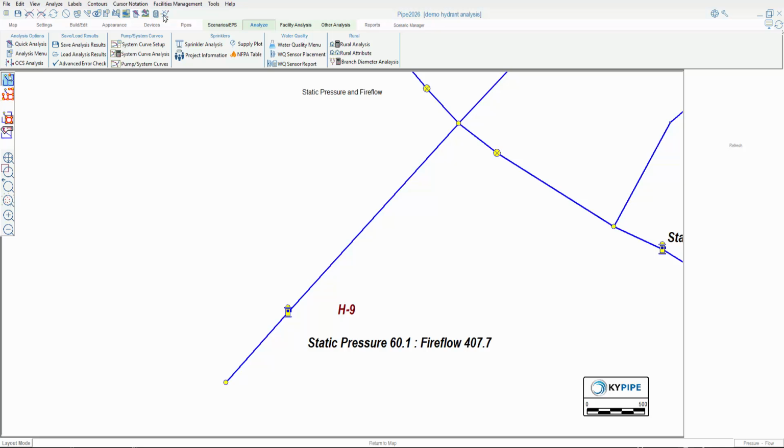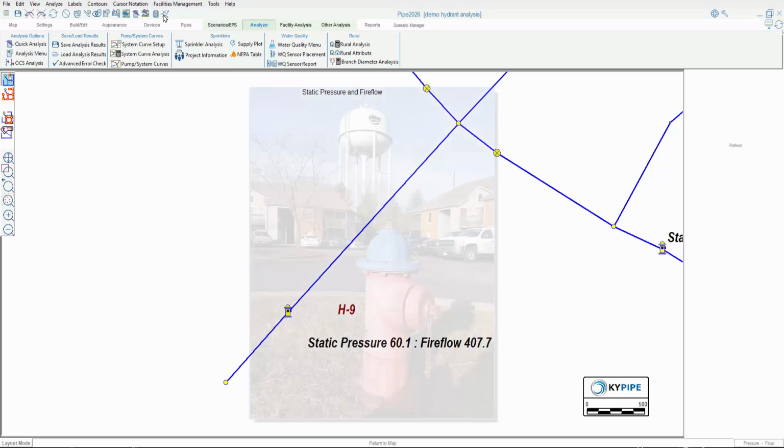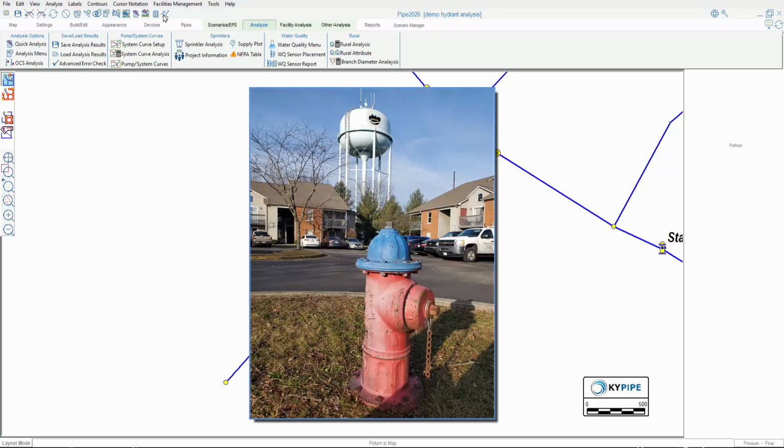One last note about analyzing a hydrant flow with no hose attached. This is the scenario that best represents a hydrant located immediately adjacent to a large pressure supply, such as an overhead storage tank. If there is an overhead storage tank proximal to the hydrant, we don't use a Fireflow with specified minimum pressure to approximate the flow.